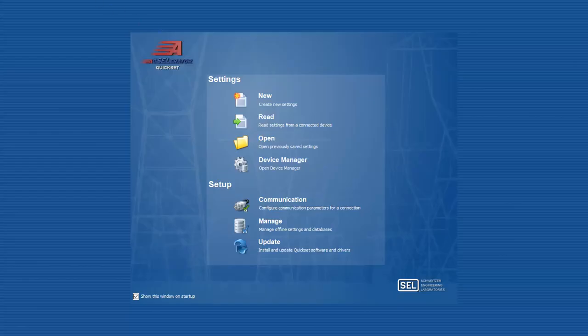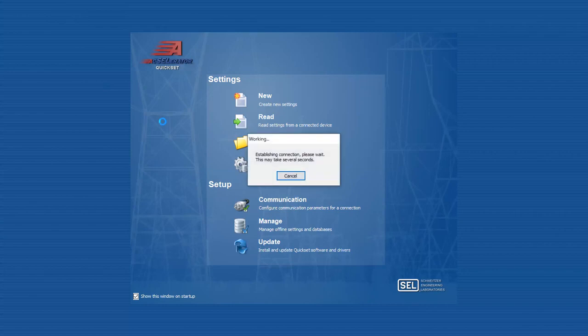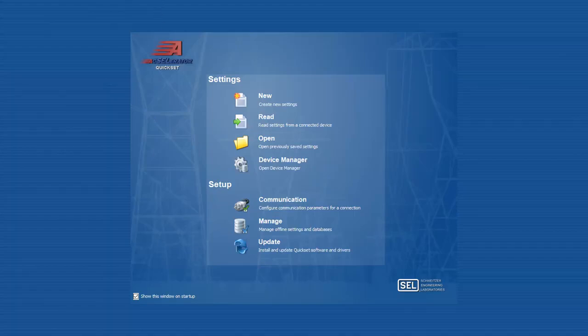So why do we need to run something called a stabilization test? The reason I do this test is that we are checking the metering on the relay when I inject normal current, normal load condition current to the relay, which means there is no differential condition. The currents are balanced on both the sides. And I need to make sure that what I'm injecting is what I'm reading on the relay.